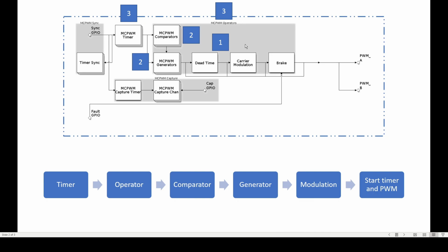Because each operator only has one dead time, you can only apply both the positive and negative delay, meaning rising and falling edge delay, to only one PWM.